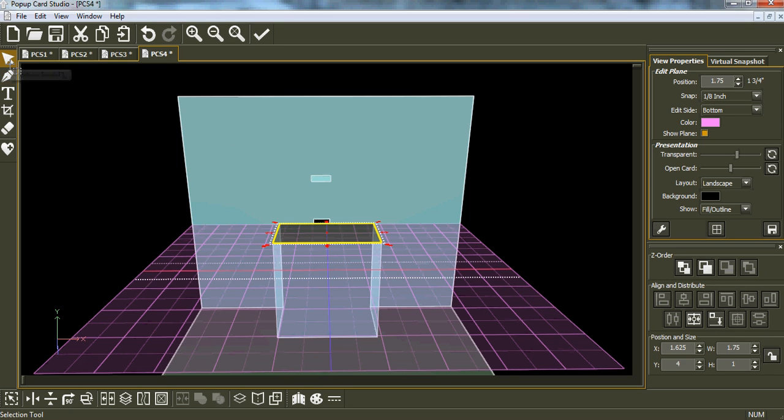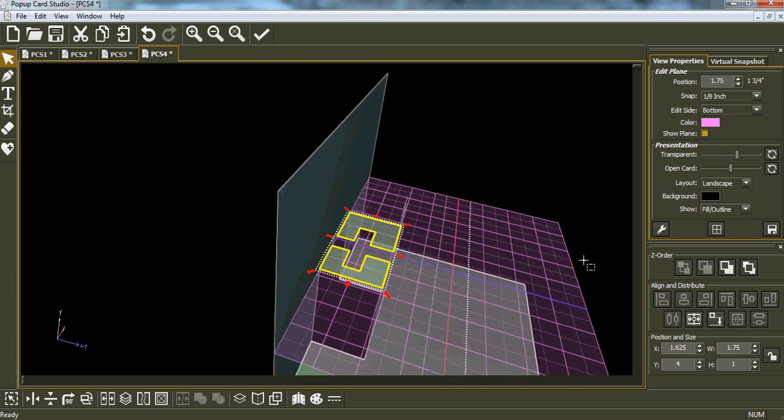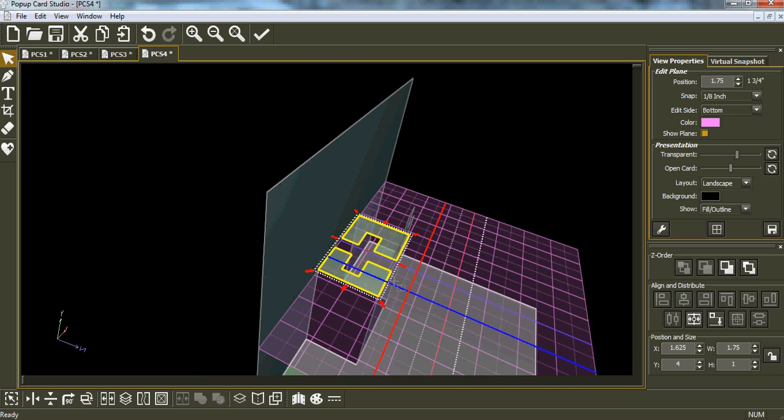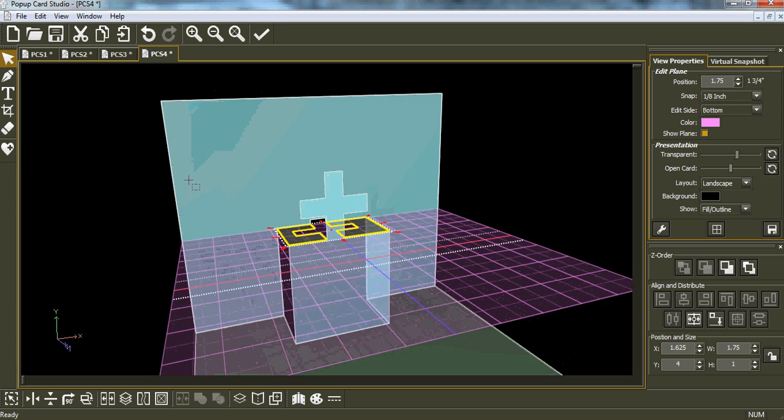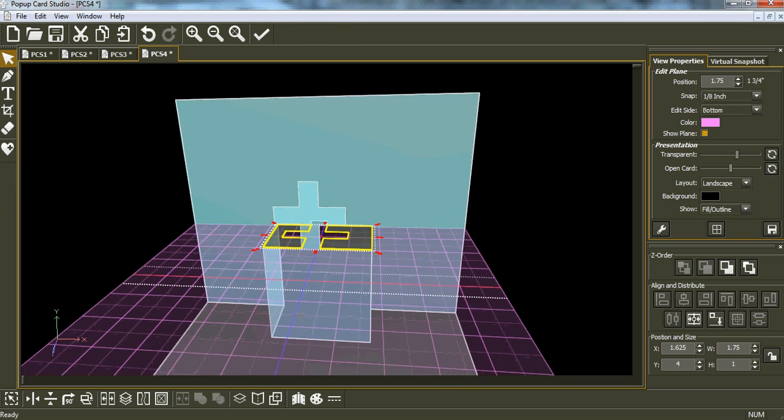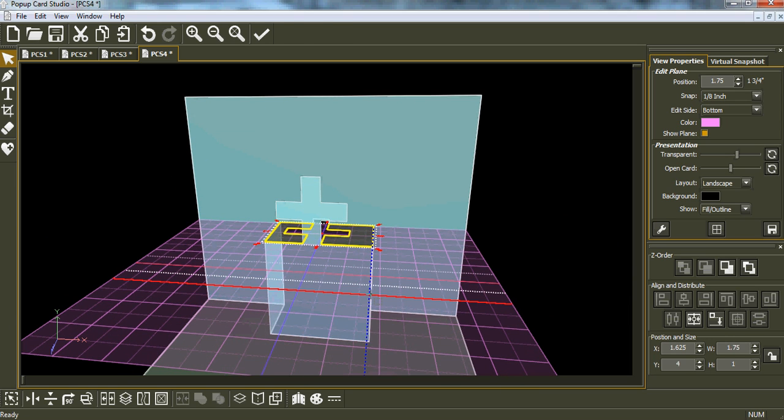So you just go back to the select key, and over here you either have the merge down, so this will merge it down one, or if you've got lots of things, you can go to the bottom, so that'll go to the bottom of everything. So then now your anchors are around your piece perfectly, and you'll find you'll use that a lot.